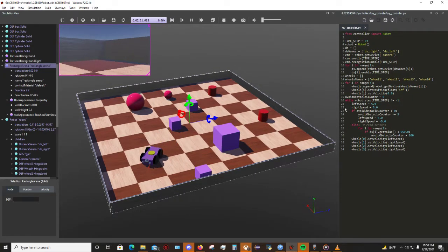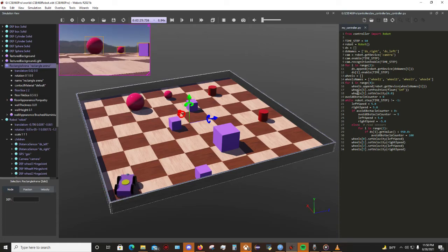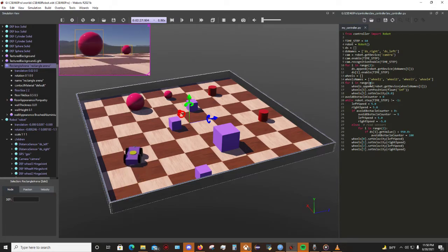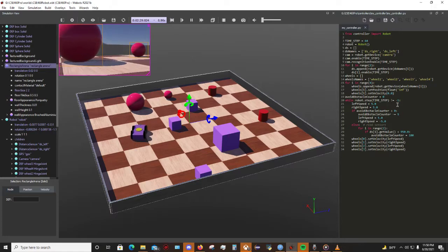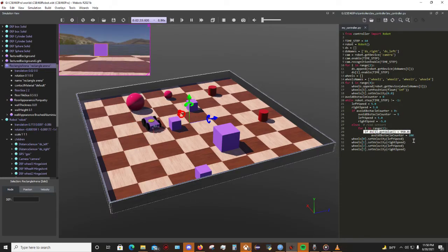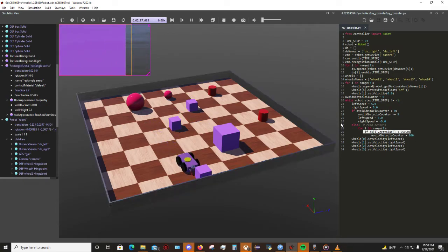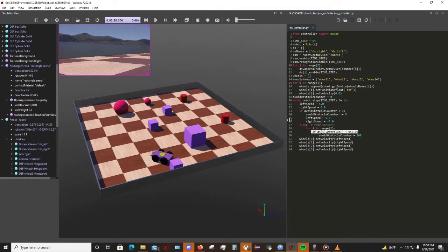The camera is for object detection purposes, and the distance sensors are always measuring distance from the robot to any obstacle. If the returned distance is less than 950, then we are considering there is an obstacle in front of the robot, as 950 is our threshold. All the four wheels, there are two right wheels and two left wheels. They are getting +5 value as their speed.